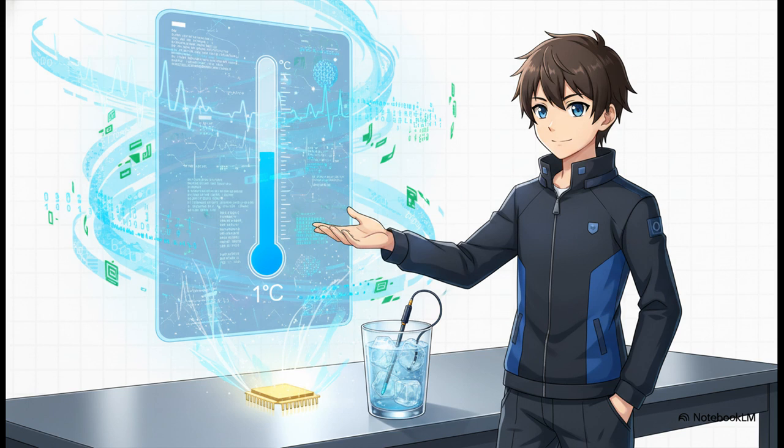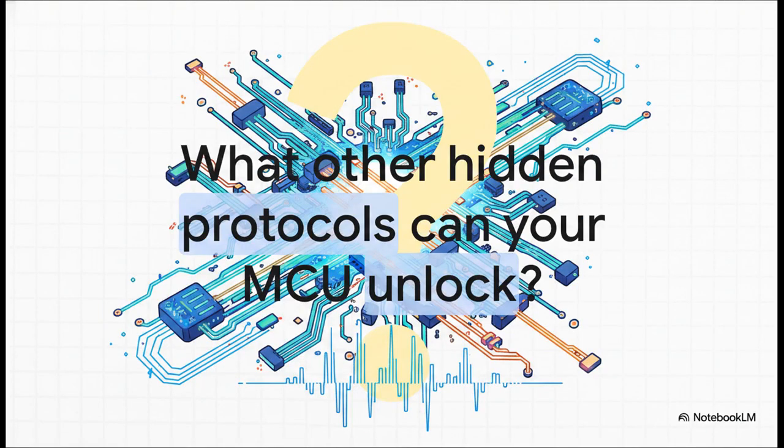It's just so cool to see it work. Mastering the underlying hardware like this just opens up endless creative possibilities. Think about it. We took a peripheral meant for basic serial text, strapped a DMA controller to it, weaponized its idle line detection, and then warped its baud rate on the fly just to speak a completely foreign sensor language. It really leaves us with one pretty big question. What hidden protocols will you hack together next?